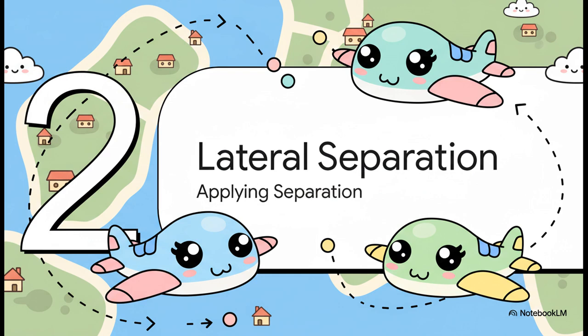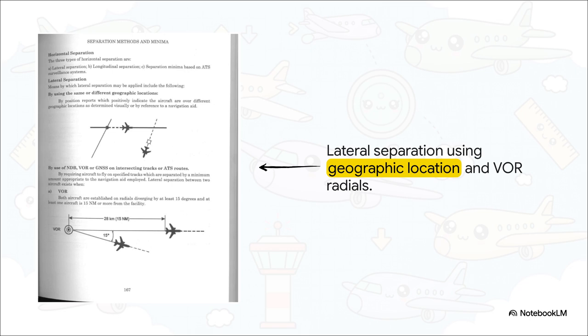All right, Section 2, applying lateral separation. The most fundamental method here is geographic location. Just position reports confirming aircraft are flying over entirely different tracks. But the exam loves testing navigational aids. Take a look at the VOR diagram. The blue regulatory rule is this. For lateral separation using a VOR, both aircraft must be established on radials diverging by at least 15 degrees. But wait. Angular divergence alone isn't enough. You need actual physical distance to let those radials spread out. Therefore, at least one aircraft has to be 15 nautical miles or more away from the VOR facility.